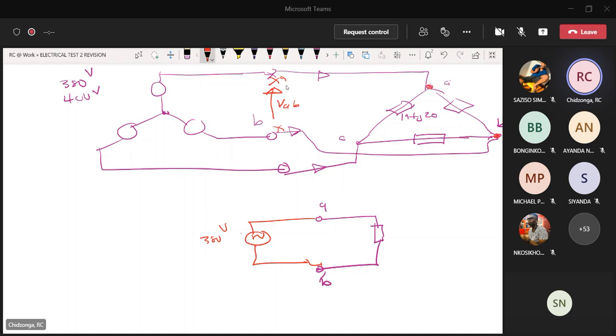And when you calculate this current here, you are calculating the current flowing in that branch. You are not calculating this current. You see, it's that current. If you want this current, then you have to go back and know, okay, how is the line current in a delta related to the phase current? So you work backwards from there, you see. But this is your starting point.